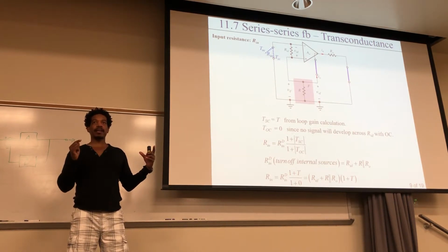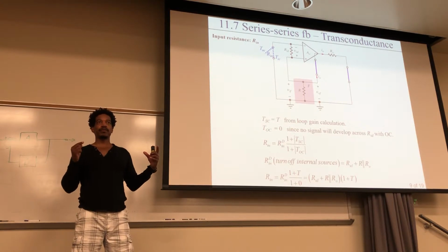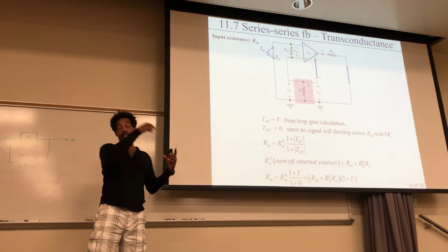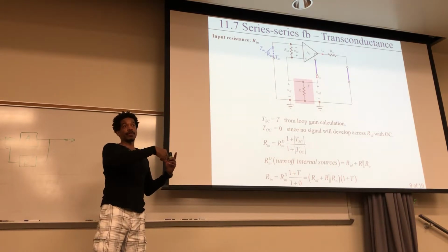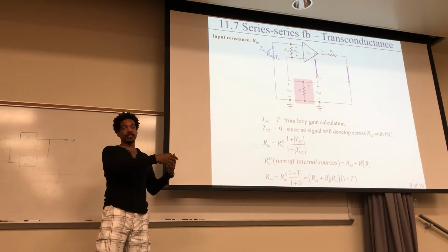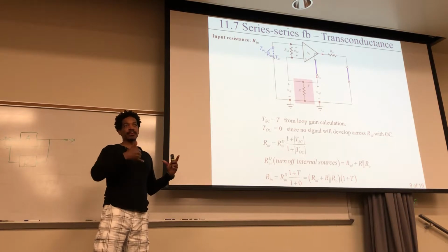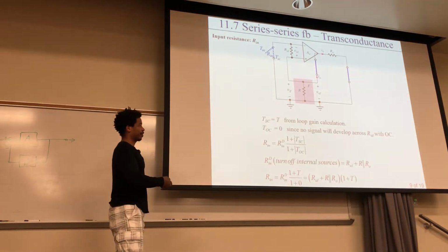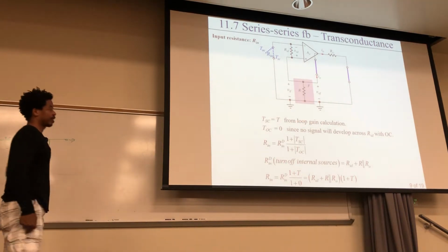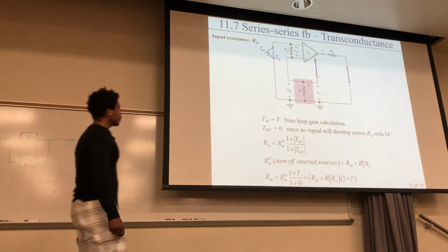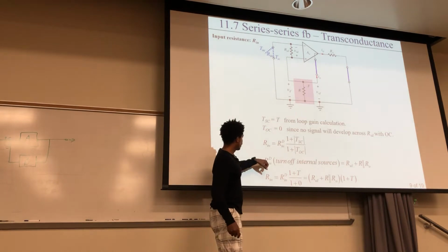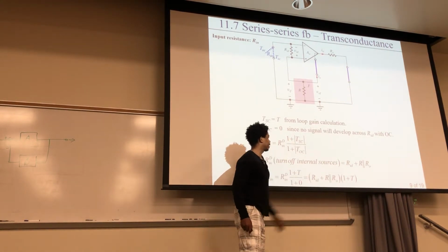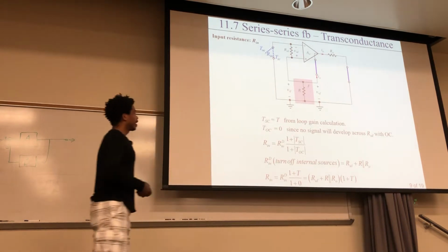And then you apply an external voltage or an external current source, which may then activate the voltage controlled voltage source or the current controlled whatever you have in there, and then that's how you determine the resistance of that. Okay, but in this case, you turn them off. So that's one thing you just want to pay attention to. So that part goes right there, and then 2 parts go right there, and then that's where you get your Rn.